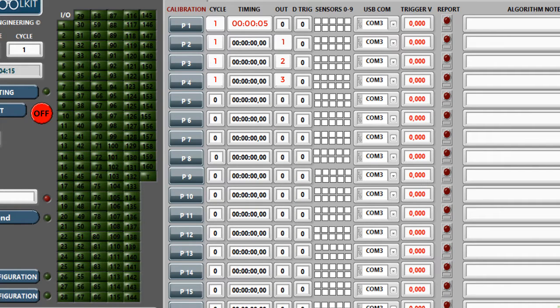The solenoid will retract and release the moving core 5 times at 1 second intervals. For such a procedure, we will set the repetition cycle to a multiple of 10. 5 inclusions and 5 disconnections, which will be equal to 1 second. It is important to consider that 1 second should be divided between the two procedures. 500 milliseconds on and 500 off. We install this instruction through the 5th port with control a 4th channel.